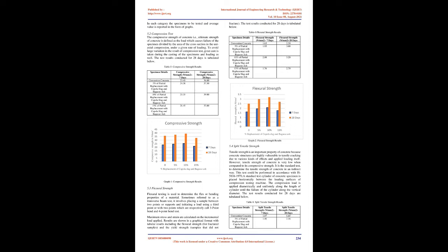Cupola slag. Cupola slag is a byproduct material which is gathered from cast iron manufacturing units. It is produced during melting of cast iron in cupola furnaces. The slag occurs as a molten liquid which solidifies upon cooling. Cupola slag is a complex solution of silicates and oxides. A cupola furnace is a cylindrical-shaped melting device used in steel industries for melting of cast iron, ranging from 0.5 to 4 m in diameter.